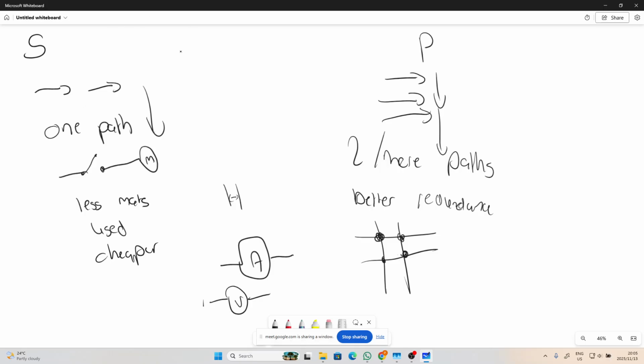When we connect a voltmeter, it must always be connected in parallel. Do we know why? You don't have to know why, just know it is like that, because voltage is the same across parallel lines. And you never connect a voltmeter in series because the full amperage will be going through there, which is very bad. Simple. Must always connect it in the correct polarity, or else it will not work, or it will read negative.